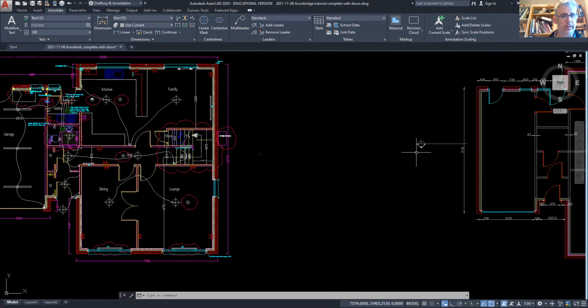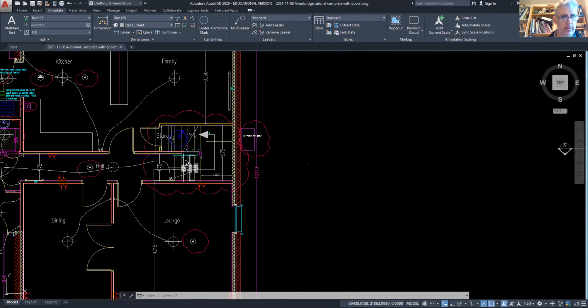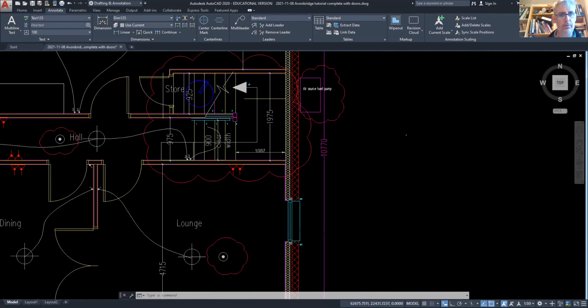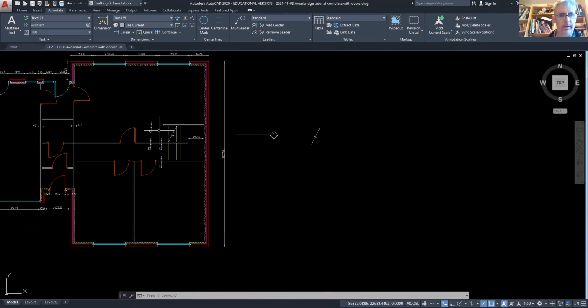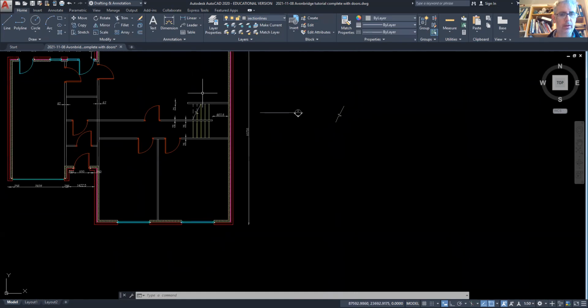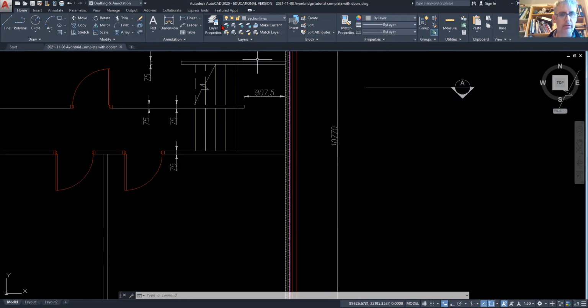Okay, so going back to this particular image, there's lots of other things we could put on here. We could put on an arrow, so I'm just going to do that right now. Again, just make sure that you're using common layers, section lines. So I'm going to put this under my section lines layer again. You could put it under a different layer for symbols. You could have a symbols layer, for example. In fact, you could have as many different layers as you wanted.